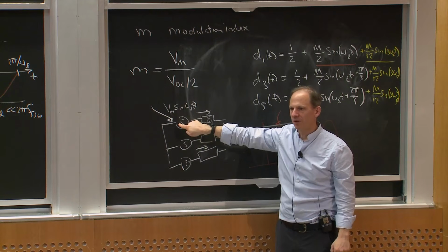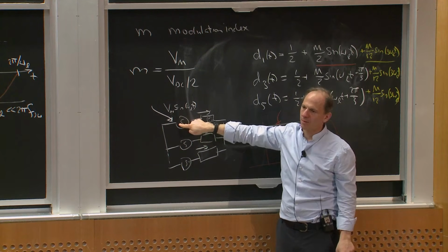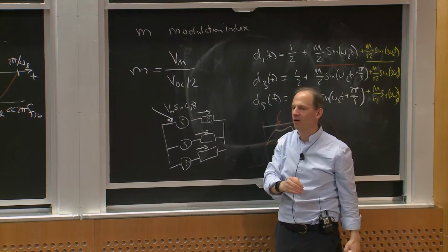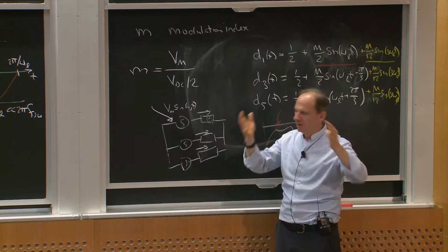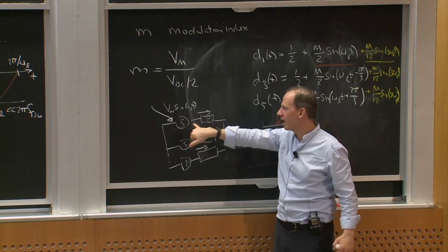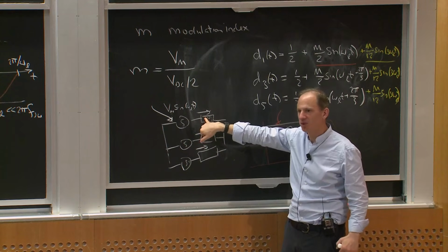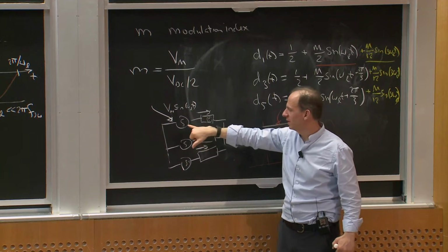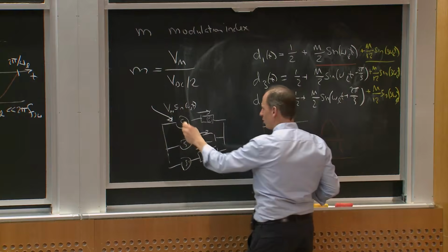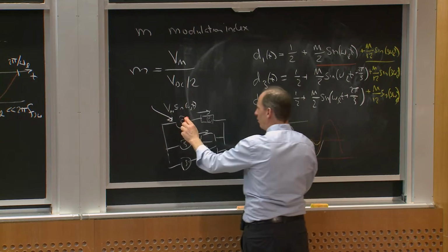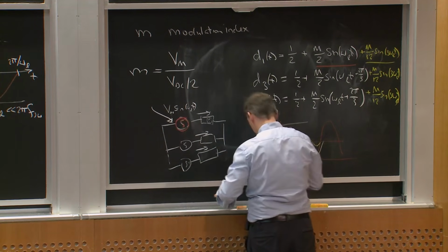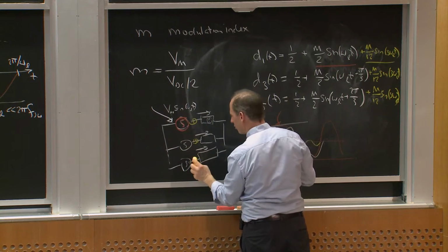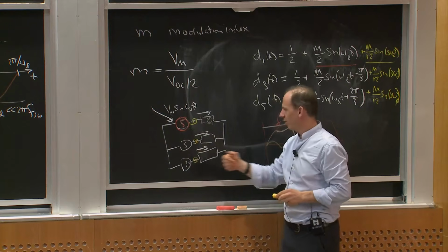And the problem with not doing this third harmonic trick is that if I try to turn up the duty ratio more, I get a lot of low frequency harmonics. I get third, fifth, other content in here, which is then going to drive low frequency content in the machine. Okay? What this trick lets me do is create the fundamental, plus some third harmonic here, third harmonic here, and third harmonic here, but the third harmonic elements all cancel.